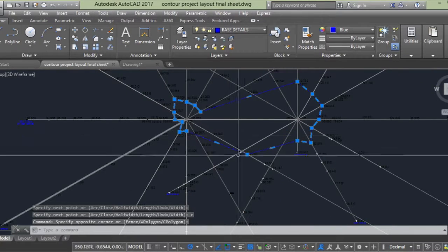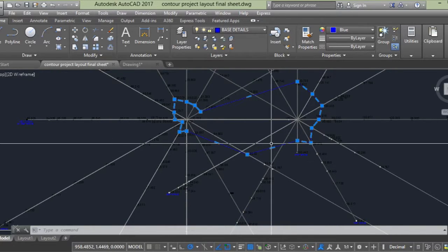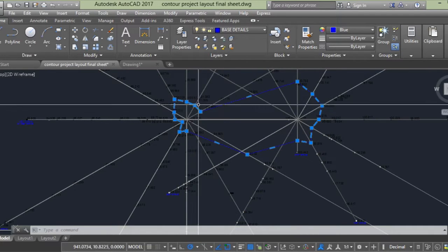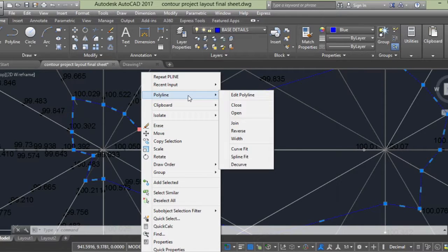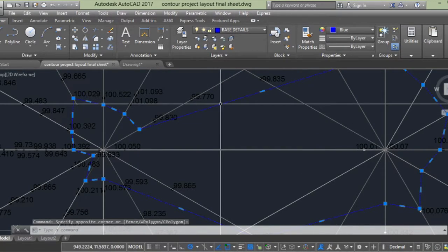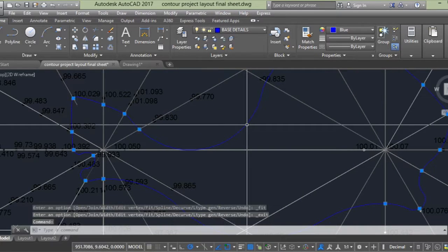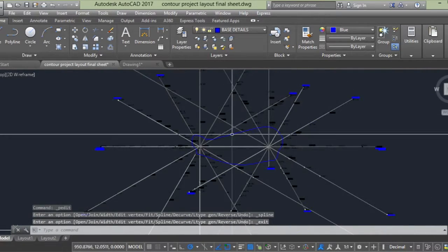Now, this is just an eye estimation, as my computer wasn't supporting the recording as well as AutoCAD, as it consumes a lot of resources, so I wasn't able to demonstrate it in a proper way. But the sheet that I drew was much better and much more accurate. And now I'll click on that, go to polyline and take a curve fit, sorry, not a curve fit, I'll take a spline fit, so it would be something like this.